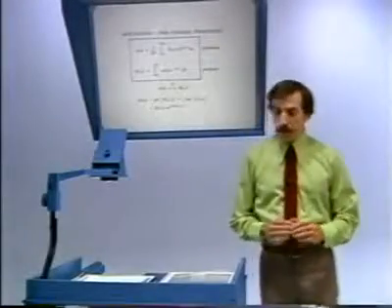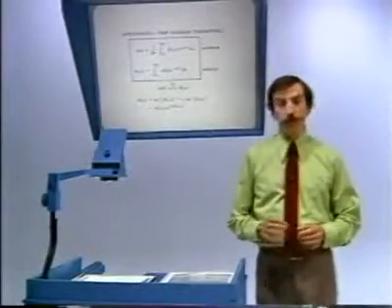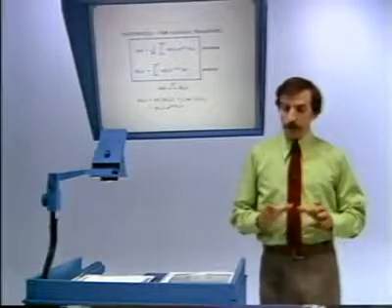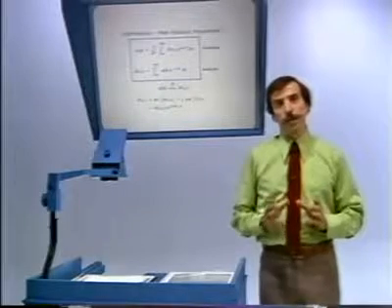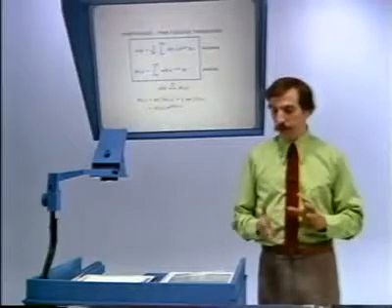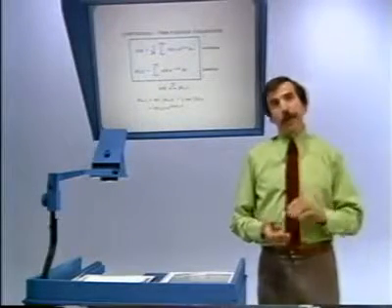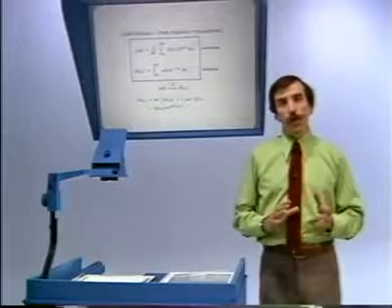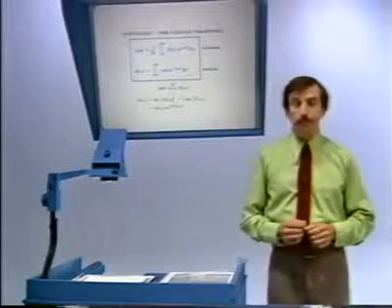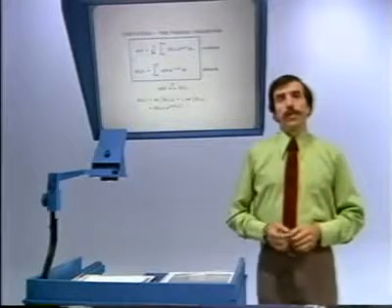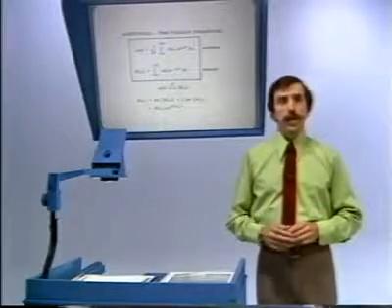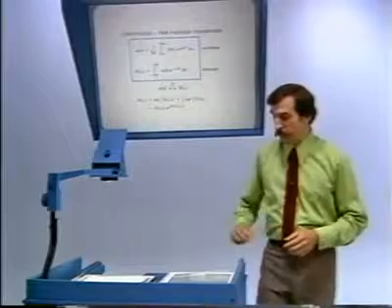In the last two lectures, we saw how periodic and non-periodic signals could be represented as linear combinations of complex exponentials. This led to the Fourier series representation in the periodic case, and the Fourier transform representation in the aperiodic case. And then, in fact, what we did was to incorporate the Fourier series within the framework of the Fourier transform. What I'd like to do in today's lecture is look at the Fourier transform more closely, in particular with regard to some of its properties.